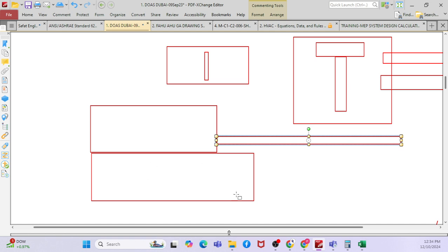So I will not go with the double wheel. I will go with a normal FAHU with the cooling coil. I can go with the horseshoe heat pipe, right? To save energy, the horseshoe heat pipe works across the on-coil and off-coil. Say the outside temperature is very hot, so this heat will transfer here. After the cooling coil, the air will be very cold, so this cold will be transferred here. You are getting what I am saying? By means of this, it will save energy.